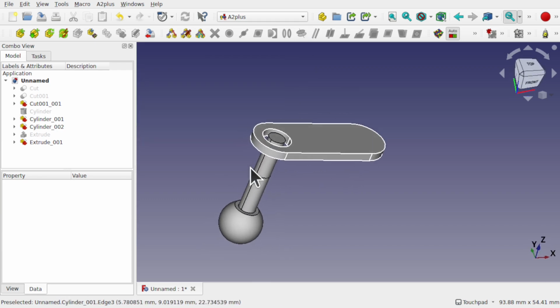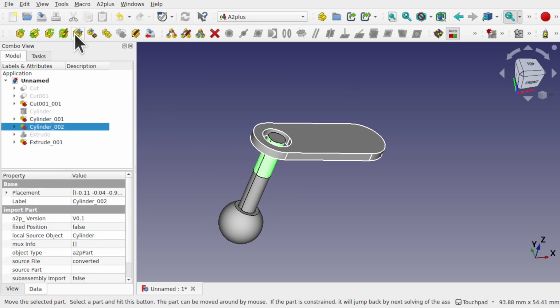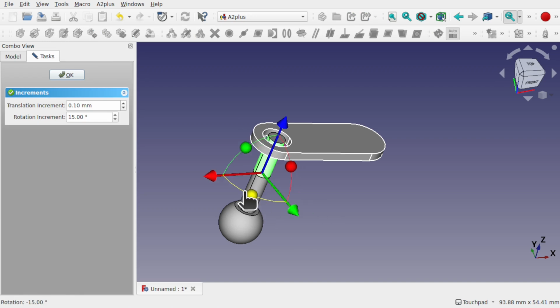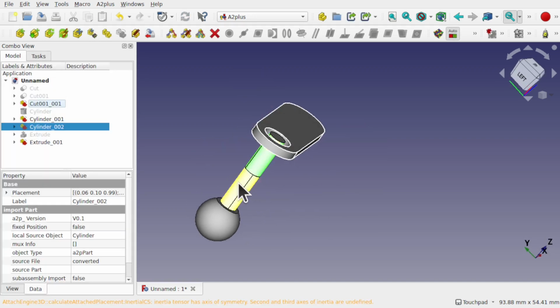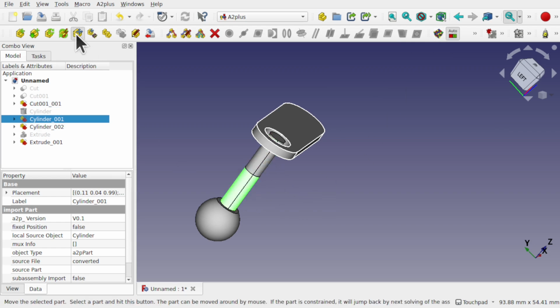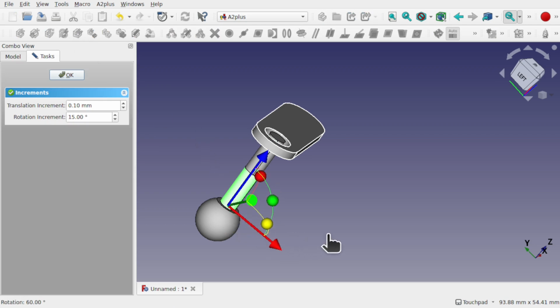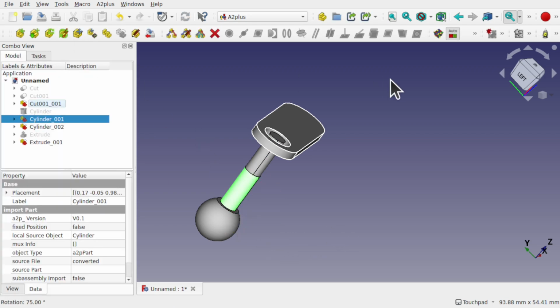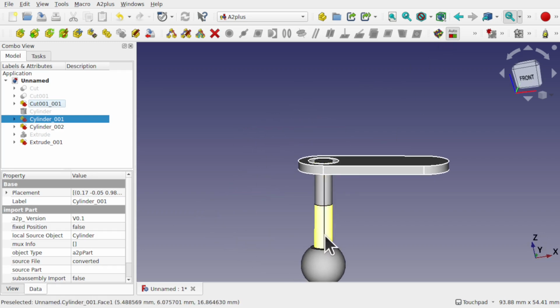So we've got the circle constraint against these. But if I click one of these and use a rotate this around to here, okay, we can see the lines aren't aligned now. The axes of those lines aren't aligned. Hit the solve, you'll see it'll flip back round. Same with this one. Okay, use the solve, and you'll see that's moved around.